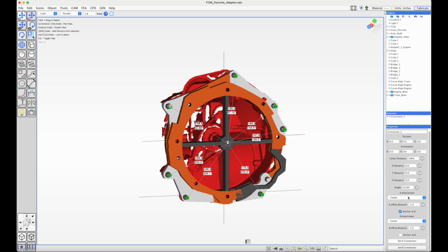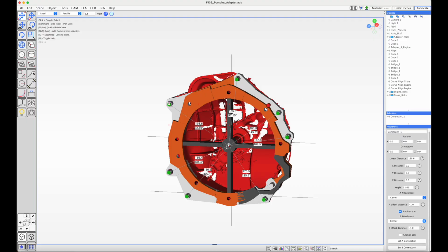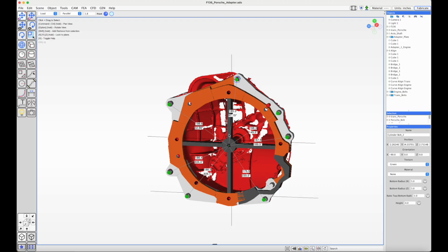And so now when I specify the anchor locations and either distance or XY offset or angle, it will use the reference from the coordinate system of the object that is anchored. So you can basically add this cylinder to the scene and then define a constraint, and it will locate it based on the anchored object's location and orientation.